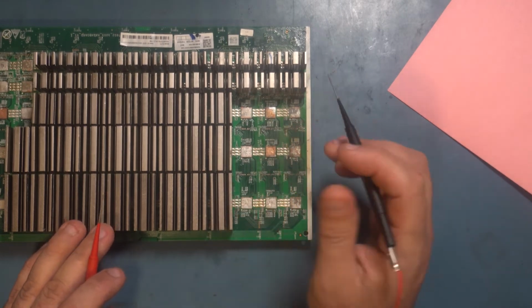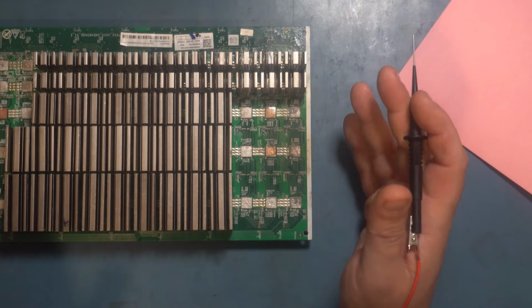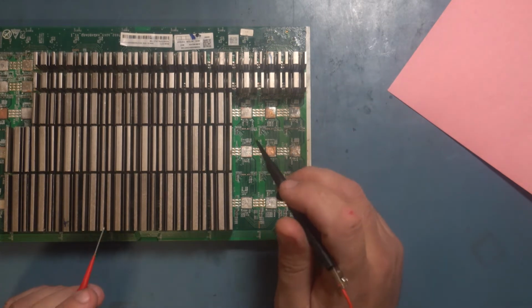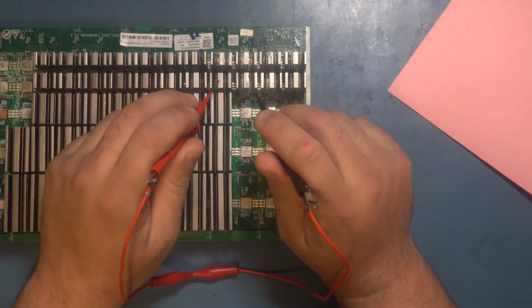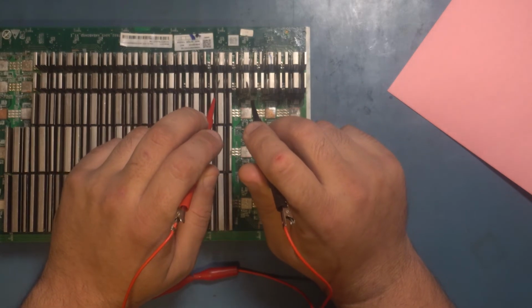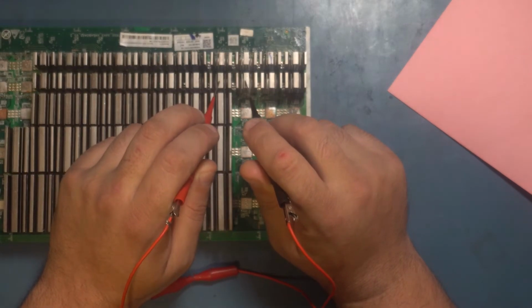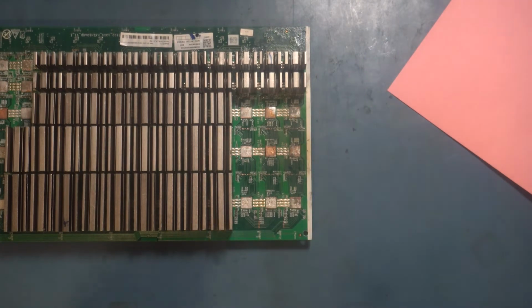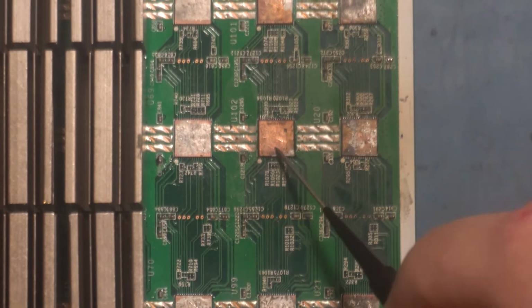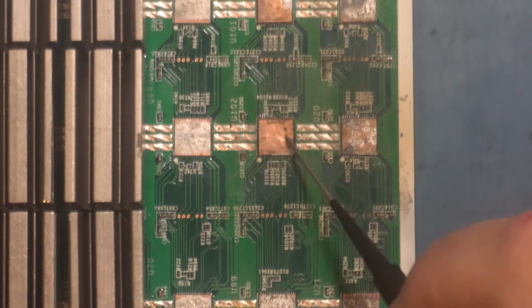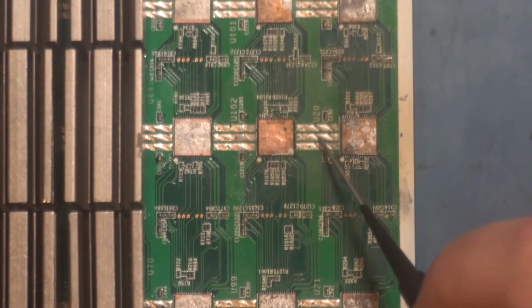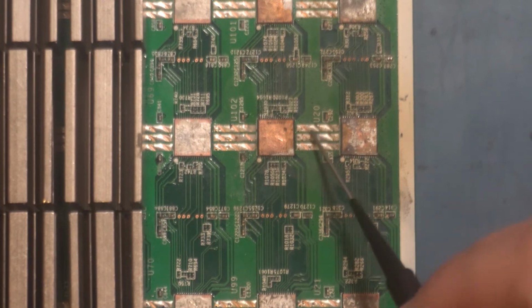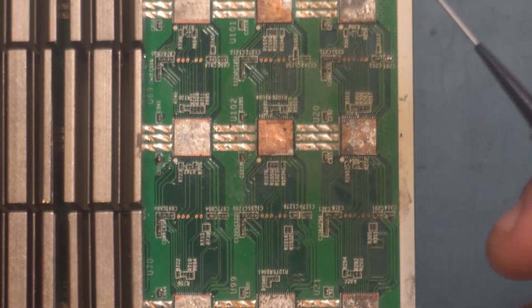And so one thing to keep in mind is that you gotta check your power, right? Checking domain voltage through the top of the heat sinks is 80% of the time a good way to do it. But there are some cases that I've seen where the top of the chips is not connected electrically anymore to the actual ground of that chip. So something to keep in mind, and the chip still works fine.